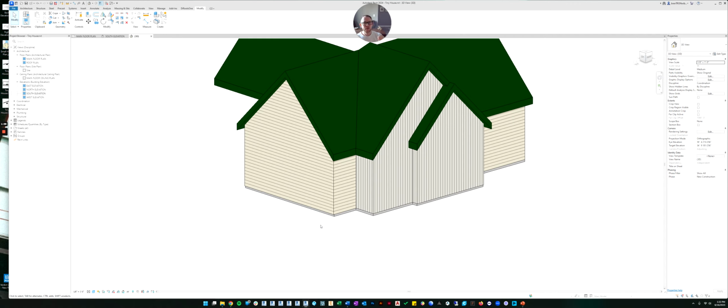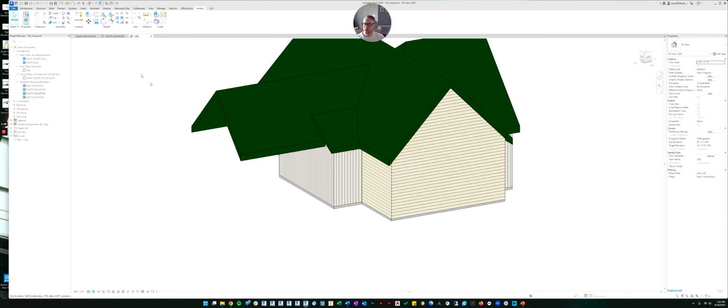We would make a new floor and we would call it a finished floor. And instead of being 4 inches thick, it would just be, like tiles, maybe 1/4 of an inch thick. So we'll make a 1/4 of an inch floor and we'll assign it a tile pattern. So let's go ahead and do that.